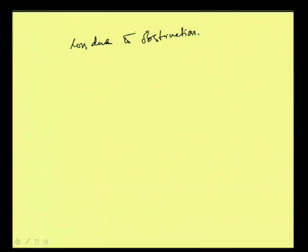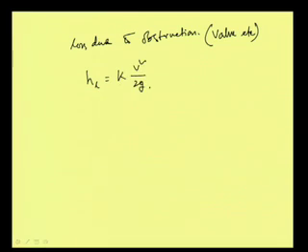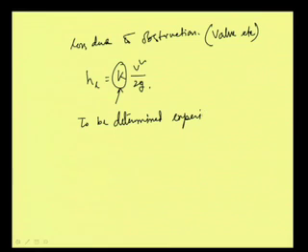So, we express any loss in this form, say valve, etc. Loss due to obstruction means it can be a valve, etc., and that head loss HL we give as K V square by twice g. And this K is the coefficient that we need to determine, to be determined experimentally.